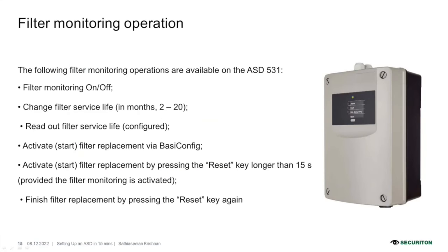Good. With that note, I also have to mention the other additional features that we have with this ASD, which is the DIP switches. As I mentioned, there are three main buttons for commissioning, and another additional one would be the filter monitoring option. Even though the filters are not practically monitored, we can set them as monitoring. That means we give them a timeline that it works for a certain period of time according to the condition where it's working, for example, from a data center, a clean room, a warehouse, or a dusty environment.